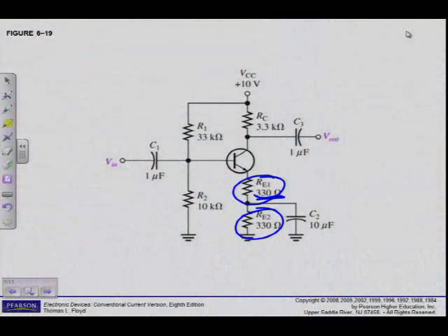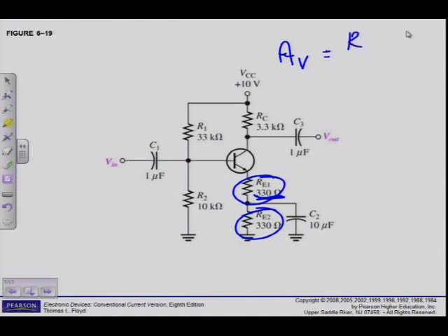Everybody uses the same book. Then we can just simplify this formula to RC over RE1. But please keep in mind, if I look at example 6.7, there is no load resistor. Again, if there's a load resistor, then I have to calculate R lowercase c, which is RC in parallel with RL, which also influences my voltage gain, of course.